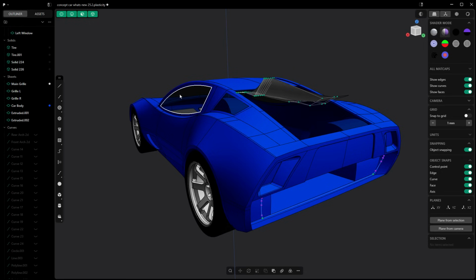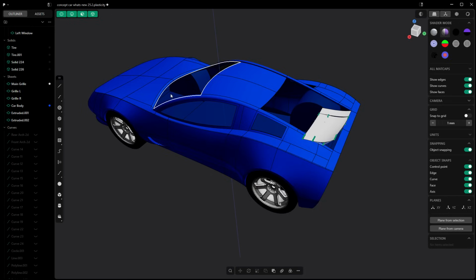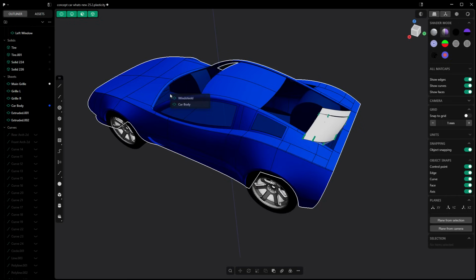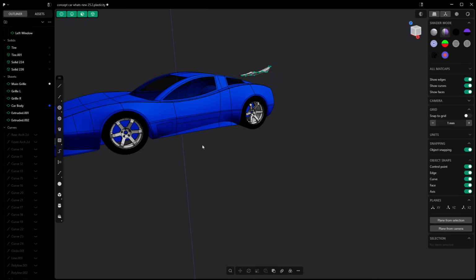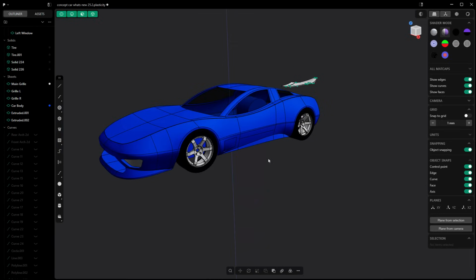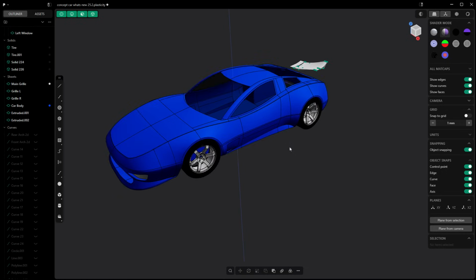Well, the new addition here is we can hold down Shift and Control and left click, and that will bring up all the things that are underneath the cursor, just like holding down the left mouse button and scrolling the wheel will. So that's a pretty cool way that we can get access to it now. Especially if holding down the left mouse button and scrolling through the mouse wheel is not a comfortable way for you to work, this can help just by holding down Shift and Control.